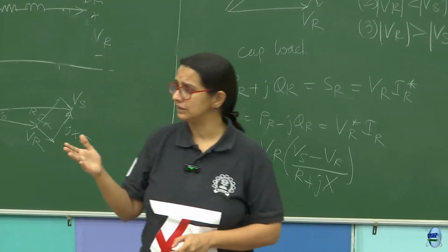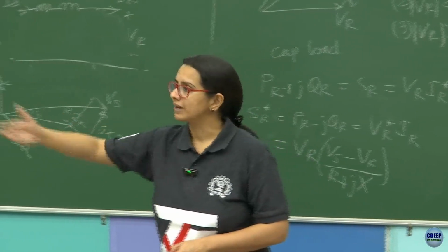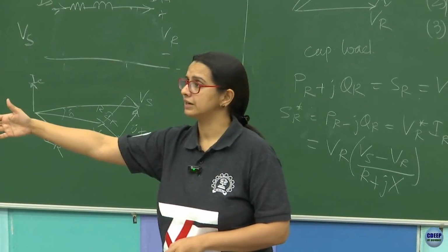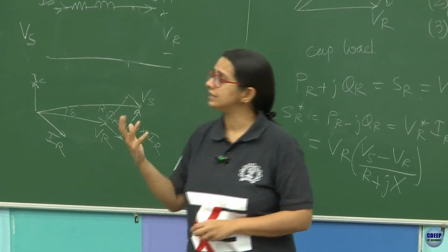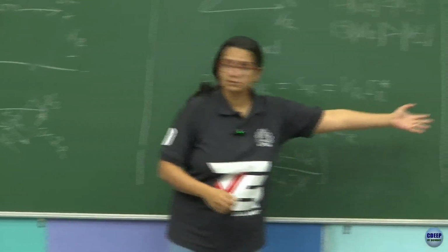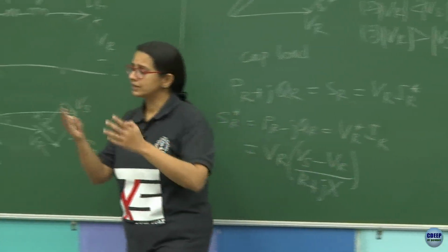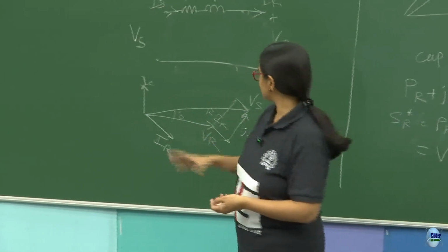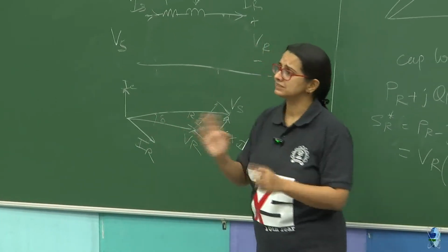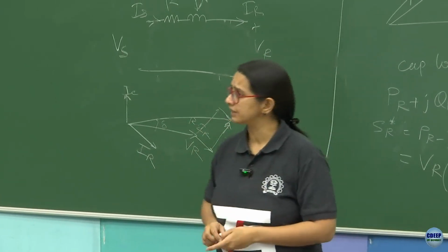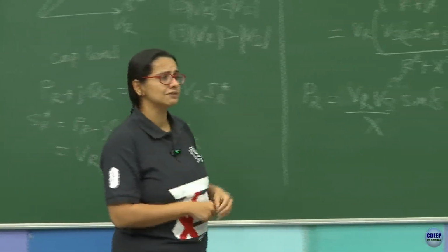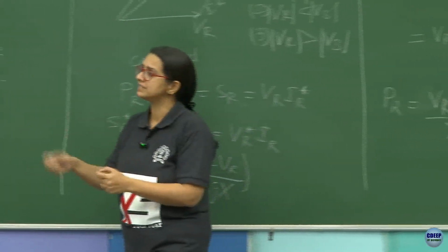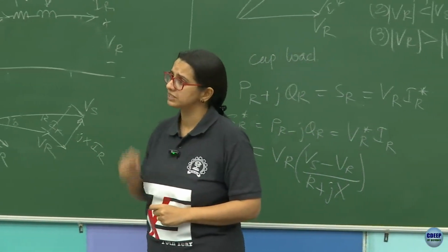We started the first class with an example. If you guys recall, I told you 150 megawatt is the limit on that transmission line. How do operators decide 150 megawatt? They're going to look at these sort of equations, and they're going to figure out what are the safe limits, the safe delta separation that's okay from a stability perspective, what is the realistic VR and VS we are going to see on the system by all the measures we know we could put in place for voltage correction.